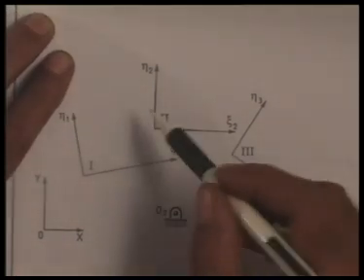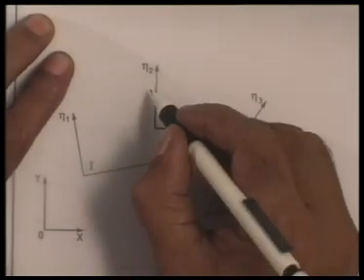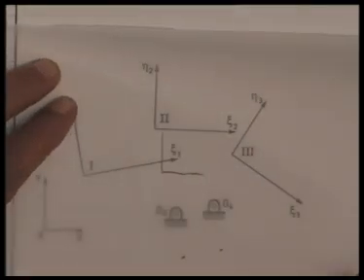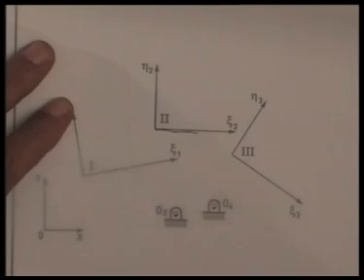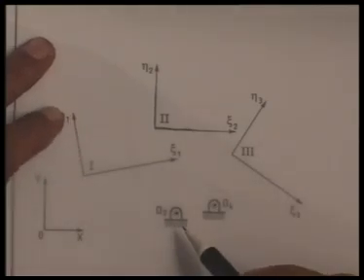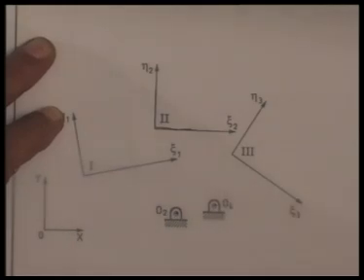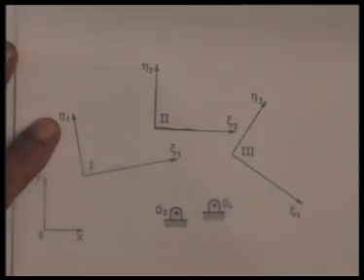So I have drawn this eta 2, zeta 2 axis on the tracing paper, as you can see here, and mark the position of the fixed pivots, given fixed pivots O2 and O4. The same relative movement I consider as if the coupler has not moved from the first position.